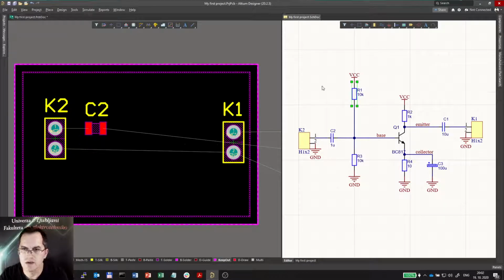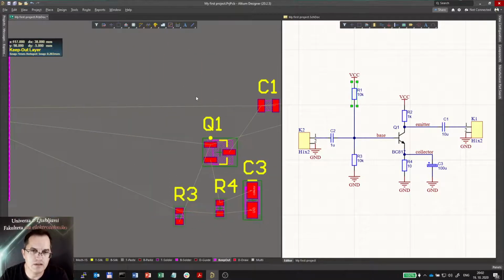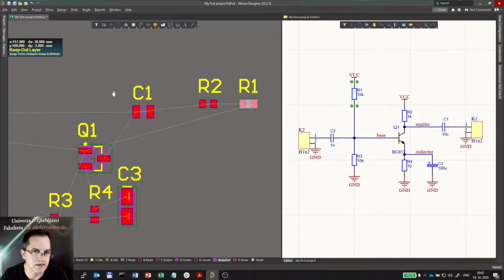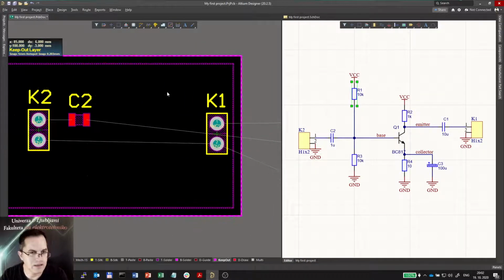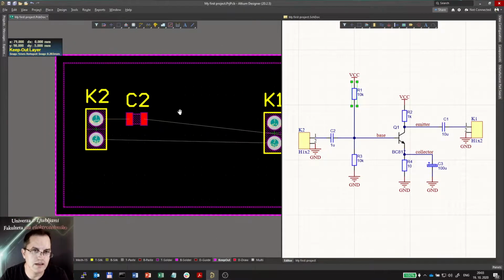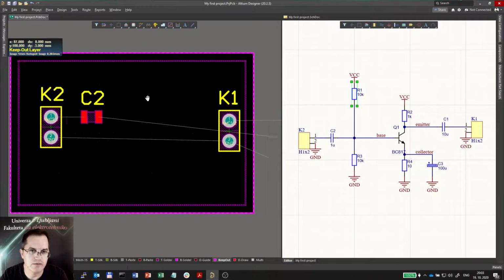So what I can do is use the so-called reposition selected components function. How does it work? I select a resistor here, go to PCB, click once, only once, and I know that a corresponding component is still selected there. How do I move the PCB left and forward? I click the right-hand mouse button and hold it, and then I can move the PCB left and forward.